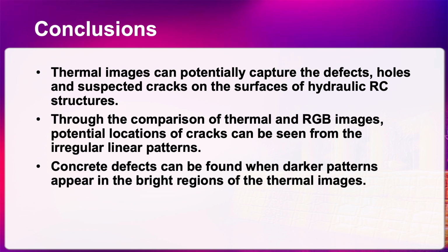So for our initial stage, we have several conclusions. We found that the thermal image can potentially capture the defects, holes, and suspected cracks on the surface of the hydraulic concrete structures. And through the comparison of the thermal image and RGB image, we can identify the location of the cracks.